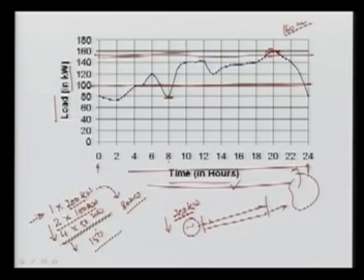If you are going for 1, then the capital cost per unit kilowatt is less compared to 4 units. So the cost of installed capacity will be reduced. At the same time, the operational and maintenance cost will be less, because here you are going to maintain 4 units, whereas here it is only 1 unit. So maintenance cost will also be less. So there is always a compromise between smaller units and larger units, and then we always make a compromise.